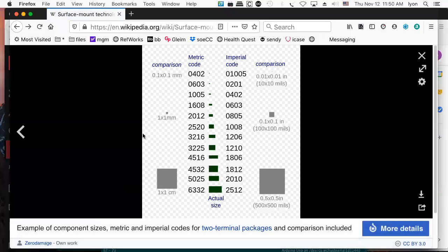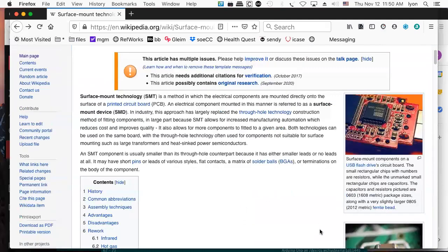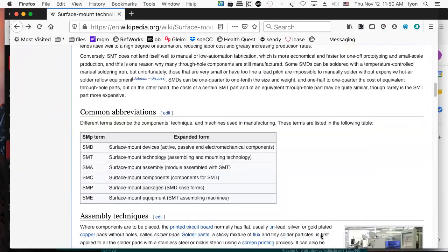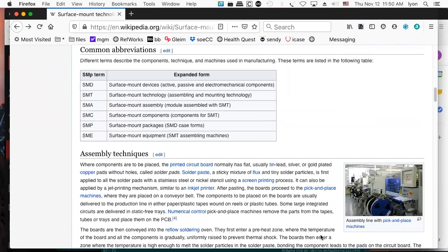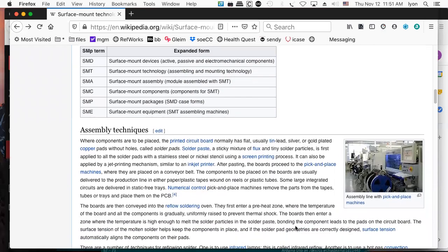I keep two kinds of microscopes handy. One is a binocular optical microscope, and the other one is a USB microscope, which I use for display work and recording. And if I really get into this stuff, I'll also keep my very, very powerful reading glasses on. You can go to the store and buy 2.0, 3.0 reading glasses. But if you go on eBay, you can find 8.0 and 10.0 reading glasses, which are really kind of like jeweler's loupes. And I also have a jeweler's loupe, which goes to 10x and 25x. So you're kind of putting microscopes on your eyes when you're doing stuff like that. And it gives you a lot of eye strain. So you've got to kind of watch it.